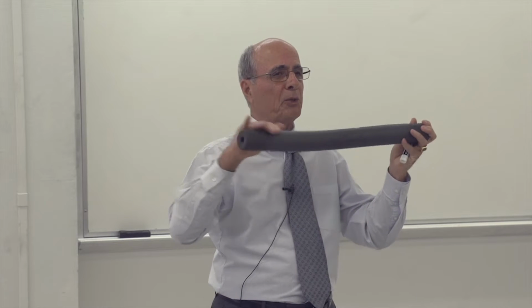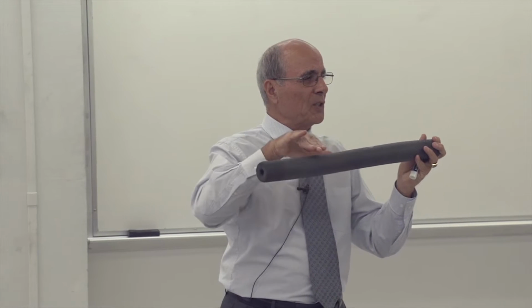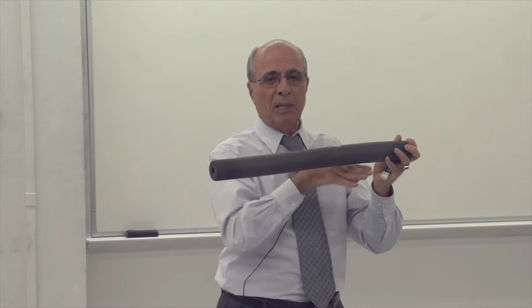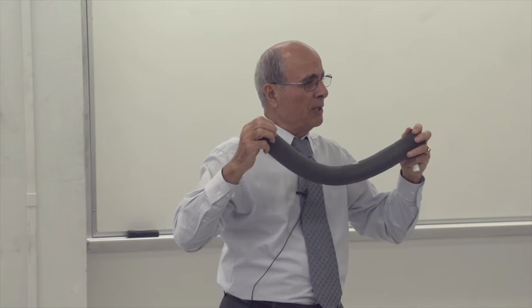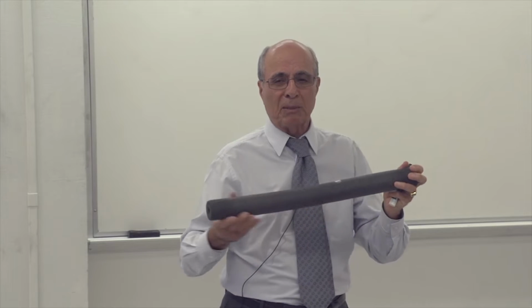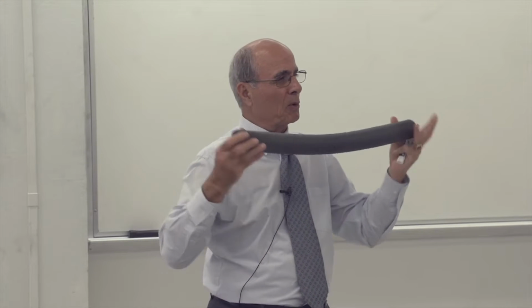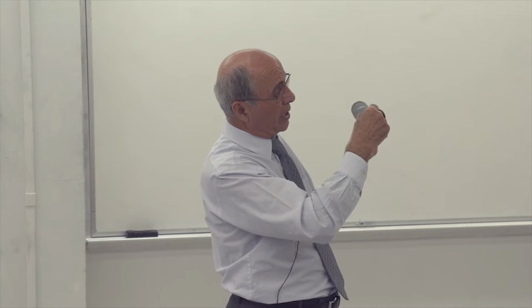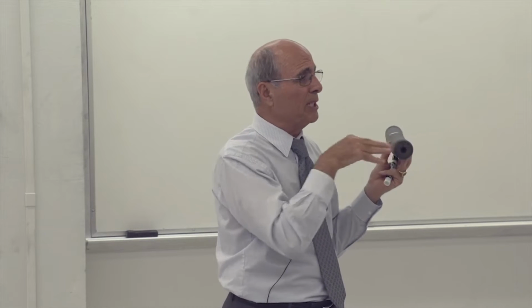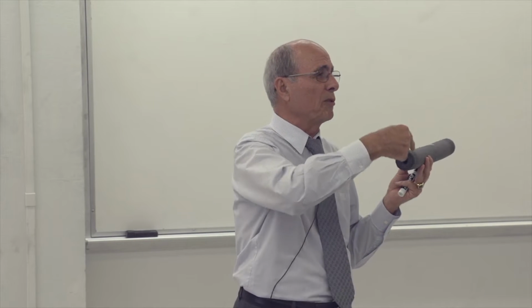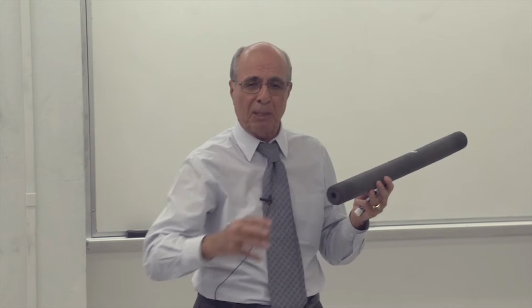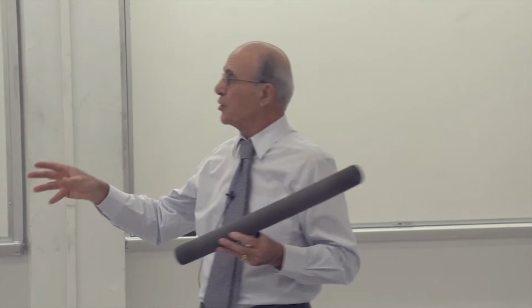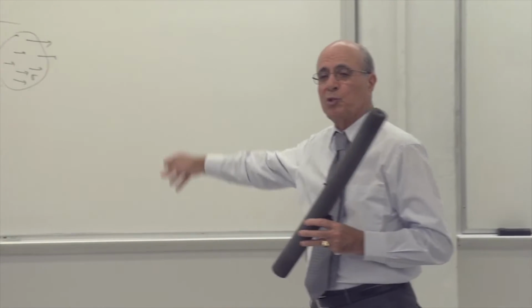Look at the top, it looks like it is getting smaller. On the bottom, it may be getting larger. So on top, it must be in compression. On the bottom, it must be in tension mode. So if the cross section here is in compression and here is in tension, somewhere in between it should be 0 too. So you are going from minus 10 to plus 10. Everybody understand that? So the stresses keep changing. So don't assume that the stress is always like what you saw in chapter 1.